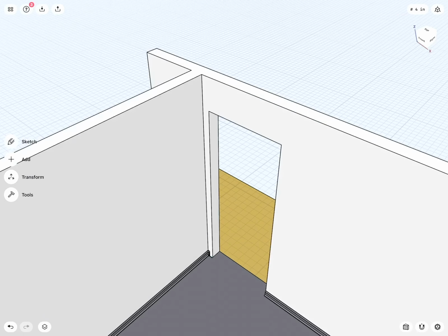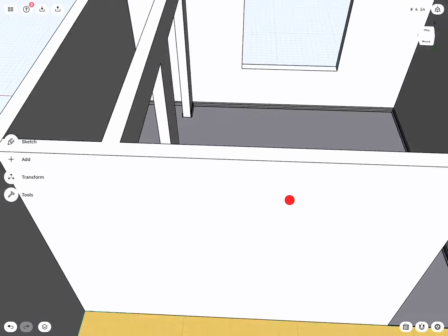When we take a look at a door, we have various elements. We have the frame that's being connected to the walls. We have the door leaf itself that's being hung inside the frame, the hinges. We have a door handle, and we also have the trim that goes around it. The trim, for example, is a cover between the door frame and the connection to the wall. The question now is, what is the best way or the proper order when to model what? And actually doing the frame first is one of the easiest ones.